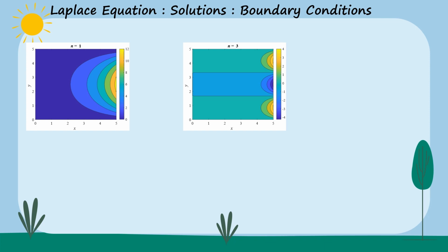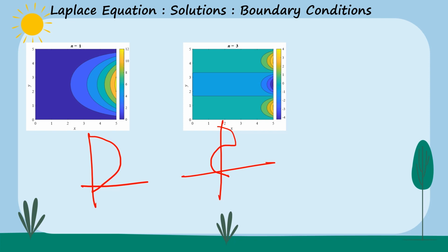What is the meaning of zero crossings? Forget everything else; I'm talking about this 1D case. It's a vibrational problem if you think of basic engineering. The first mode is a sine-shaped curve. The second mode has two crossings. The third mode will have three crossings.